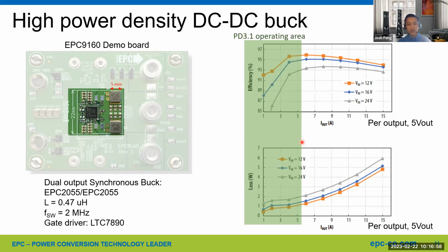But here I want to highlight one thing: the inductors, you can definitely shrink quite a bit. Typically, standard parts come with 2.2 microhenry at lower switching frequency; at high switching frequency, 1 megahertz or 800 kilohertz, you can run 1 microhenry. In this case, when you switch at 2 megahertz, you can go down to like 0.47 microhenry. What does that mean? That means your output PD Type-C ports can really be minimized, ideally putting more ports on the AC/DC charger, for example.